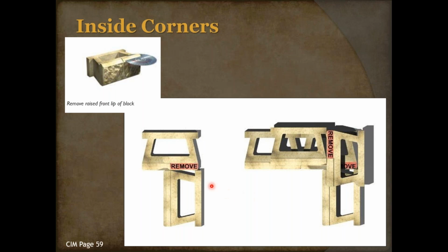One word of advice, just keep in mind as you do these inside corners, the walls tend to sit back a little bit, right? You've got that setback. So make sure you've got a little bit of block buried there, so that the next courses on top of it will rest on the block. If you simply stopped your block right here, now all of a sudden you'd have an issue. So I always make sure you've got enough block into the hillside, and that way you're not a problem.